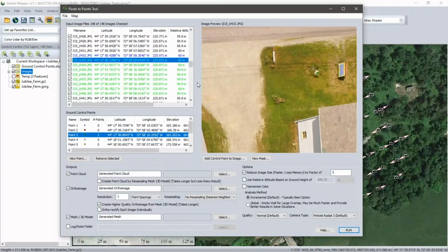Question: Mackenzie, do you need to identify the ground control point in all of those images? How many images, in other words, do you need to tag a ground control point? You should tag your ground control points in all the images in which they appear. This tagging will help to improve your accuracy, especially if you tag all of the images where the point appears. It helps to start identifying those like features and locating them in coordinate space as well.